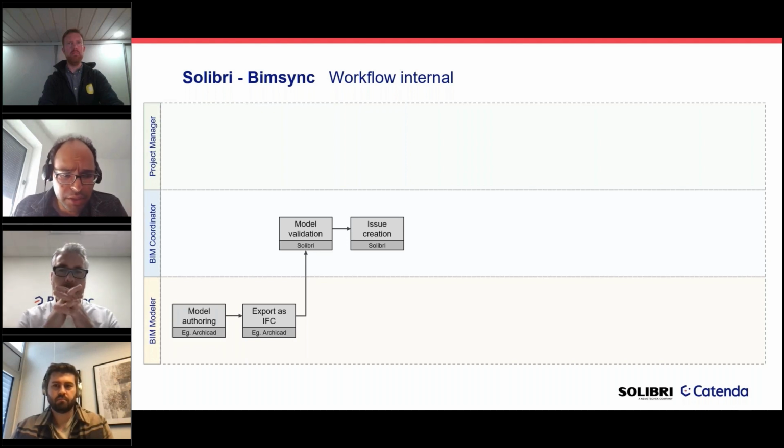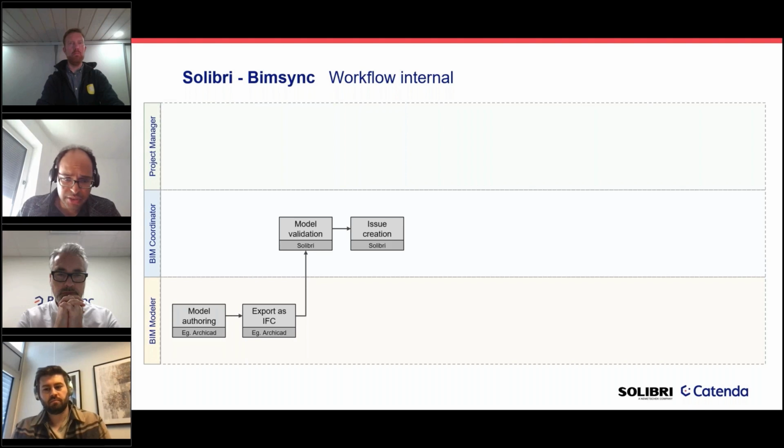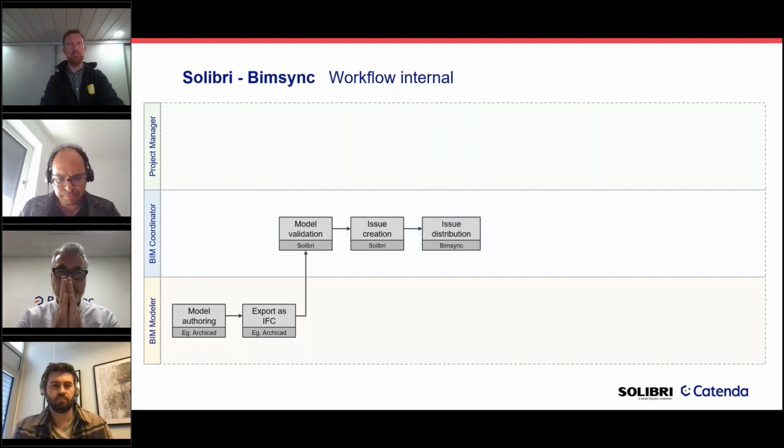So once the model validation is done in Solibri, I could do my issue creation. In issue creation, I'm not only creating the issues based on the results, I'm also assigning them to different parties, because it could be that I don't only have one modeler in the project, I have multiple BIM modelers, and each one has their own responsibility.